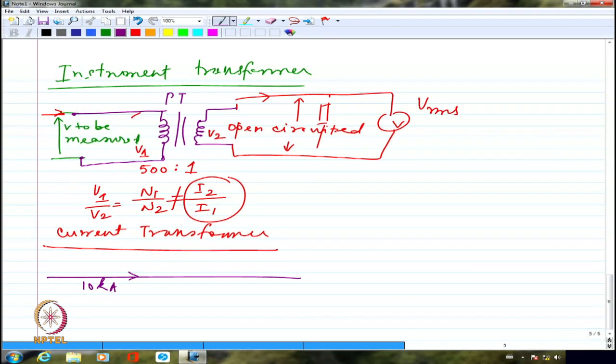And what we normally do is, around this, we put a toroid. You guys know what is a toroid? Toroid is like a bangle around which I am going to wind many turns, basically. So that is also a laminated core, which is like a bangle, and then I am going to put huge number of turns around it. So in this toroid, which is actually around this coil, I am going to make huge number of turns. These are the two terminals that are available.